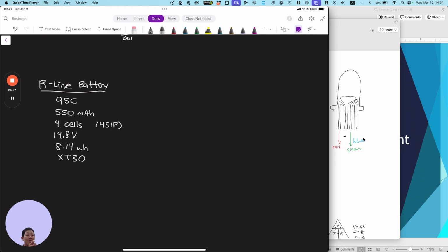The wires, maybe, the black wires? The wires won't tell you if it's parallel. It'll tell you the S, it won't tell you the P, is what I'm trying to say. Well, this says 1P, so where's that 1P at? Well, 1P is because there's only one set of these. If you had another set parallel to it and they're all tied parallel, that would be the 2P. But that's where you can't really tell the P. You can always tell the S multiple ways.